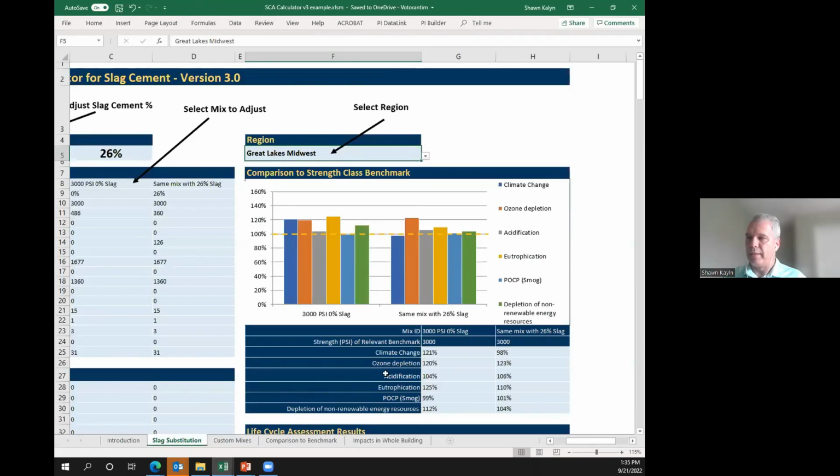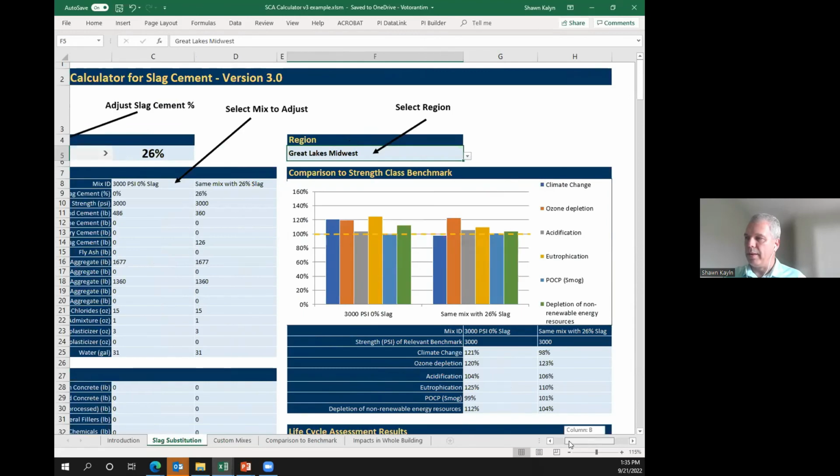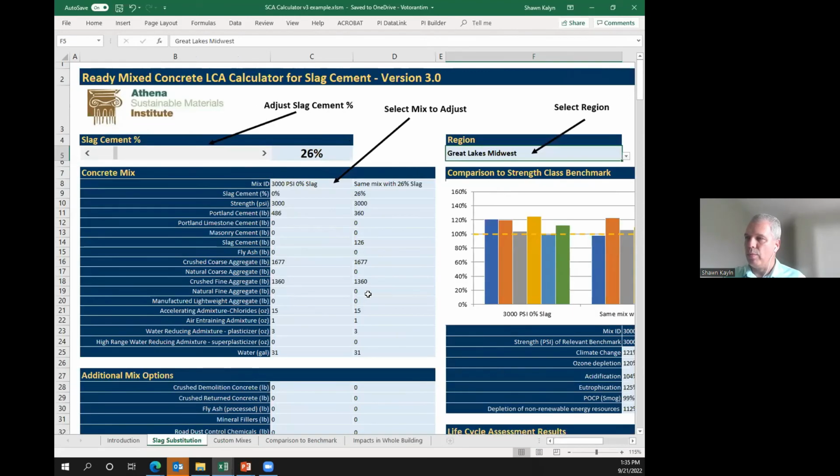In a lot of aspects, I'll just talk while you're still waiting, this tool really works well when you're looking at it from the design stage right to the production of concrete. Just requiring an EPD right off the bat in a lot of cases can be good and bad. The bad part about type 3 EPDs, or any EPDs, is it's a point in time. So it's fixed.